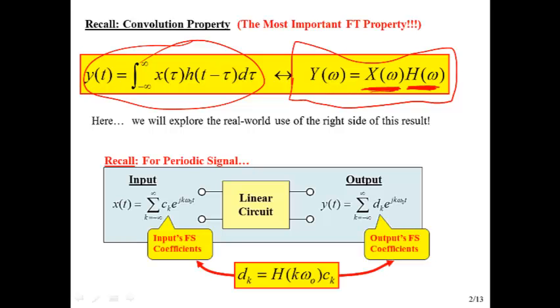We've seen this already for the periodic signal, where we break our input down into this sum, and we just have to focus on this kind of pseudo phasor at the frequency k omega 0. So C1 tells us the phasor magnitude and phase at the frequency omega 0.